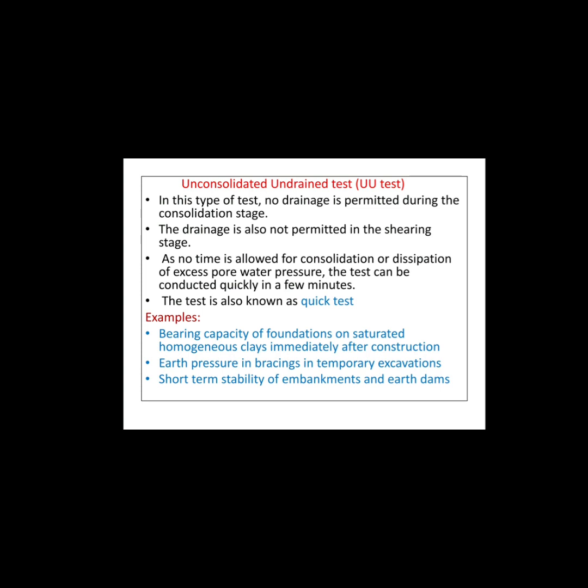The results of such a test can be used for field problems where critical stress develops in a saturated soil mass too rapidly for any moisture content to change appreciably. Examples: first, the bearing capacity of foundations on saturated homogeneous clays. Second, the earth pressure on bracings in temporary excavations. Third, the short-term stability of embankments and earth dams.